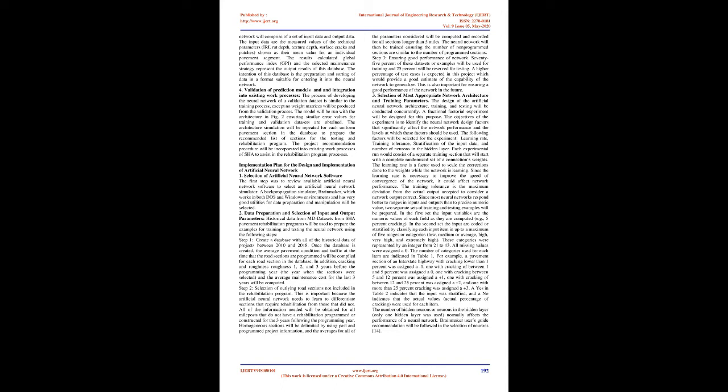Factors affecting pavement surface roughness will be used as input variables to develop a model to predict the output variable, roughness. The predicted output is compared to measured values to calculate an error used to adjust the connection weights between the model inputs and outputs. Backpropagation algorithm is then used during the training process to minimize error until the model produces a lower error value.